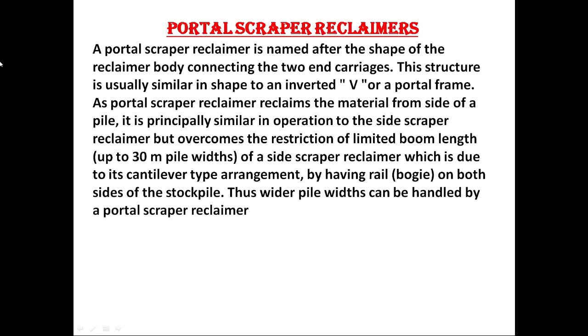up to 30 meters pile width of a side scraper reclaimer, which is due to its cantilever type arrangement, by having rails on both sides of the stockpile. Thus, wider pile widths can be handled by a portal scraper reclaimer.